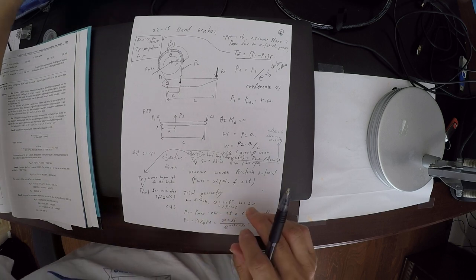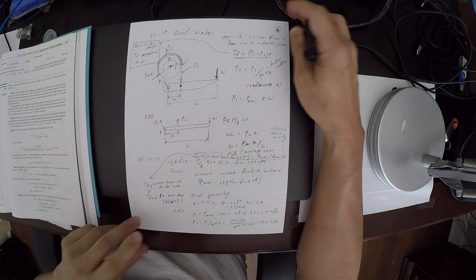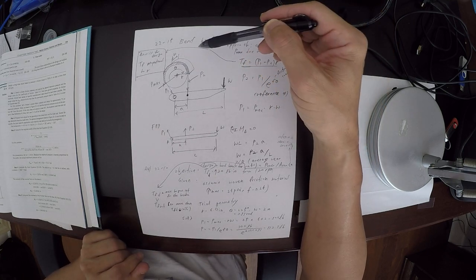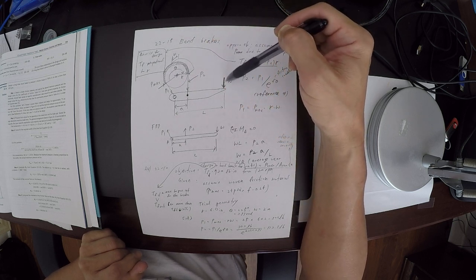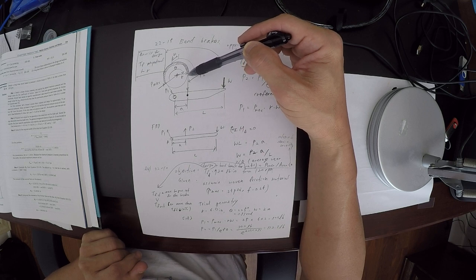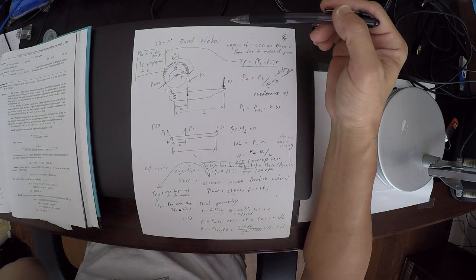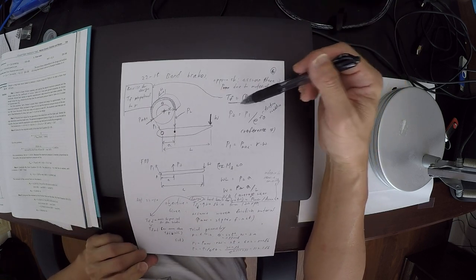So next one is the band brake. The band brake is again made to make it more efficient, and then apply less force right here by increasing the contact surface between the brake pad and the drum itself. So basically there are some equations you need to understand.